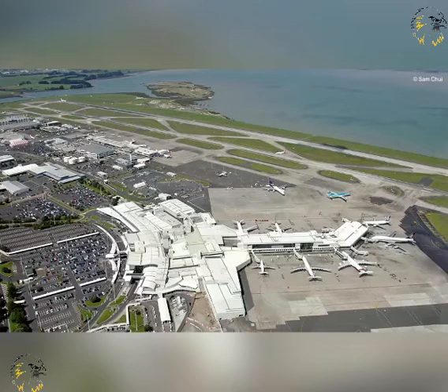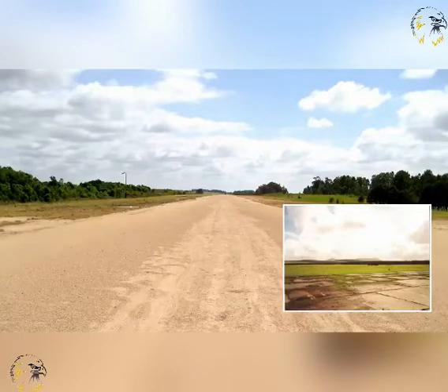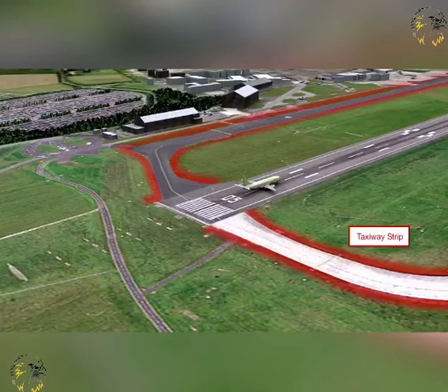The shoulders of a taxiway, used by turbine-powered aircraft, are to be prepared in such a manner that they prevent erosion by jet blast, which can cause the ingestion of surface material into aircraft engines. Taxiway strips, similar to runway strips, are provided to delineate the area to be cleared of objects which may be obstacles.